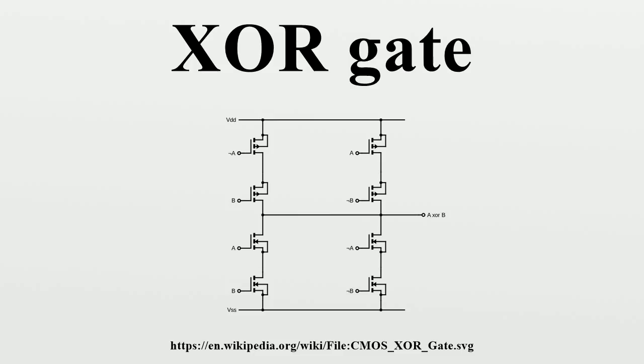XOR can also be viewed as addition modulo 2. As a result, XOR gates are used to implement binary addition in computers. A half adder consists of an XOR gate and an AND gate. Other uses include subtractors, comparators, and controlled inverters.